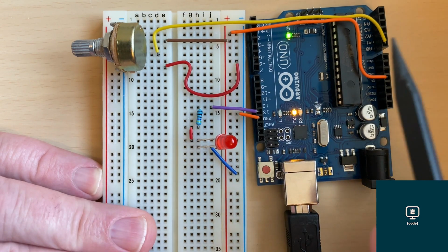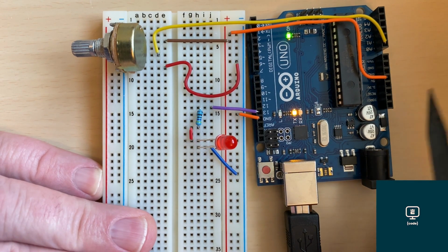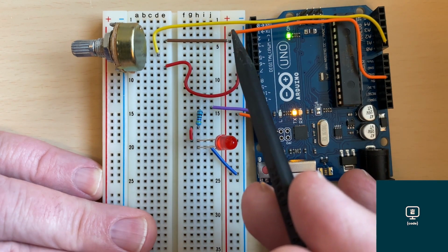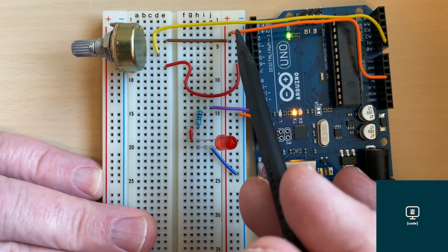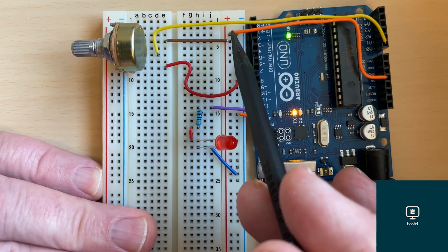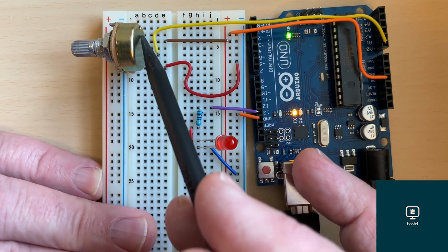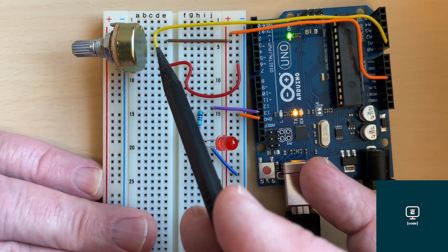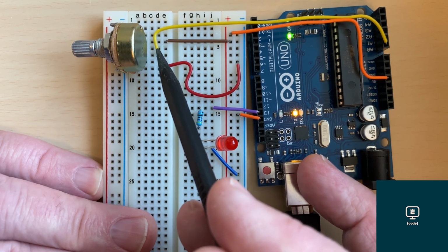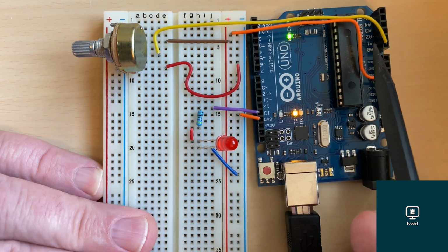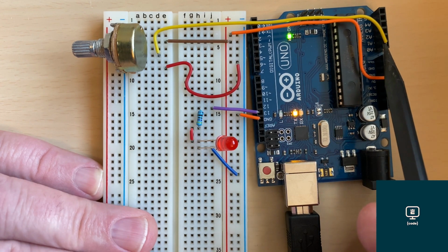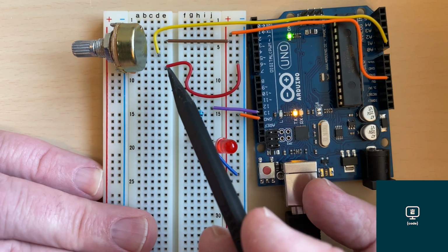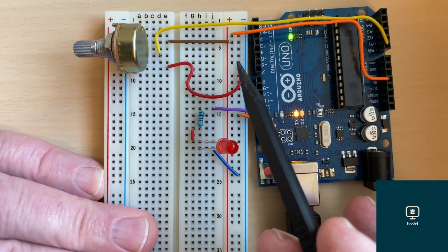Now on the other side of the board, from the power section, you're coming out 5 volts and going into that positive bus. And then that positive connection with this brown jumper here is going into row 4 from E4, which is connected to the first terminal, A4. The middle terminal is coming out of row 6 from D6 all the way back over here to analog input A0. And on the other side of the resistive element for the potentiometer, you're coming out on row 8 from A8 to E8 into the ground bus.